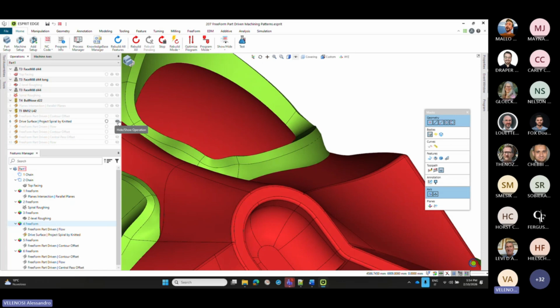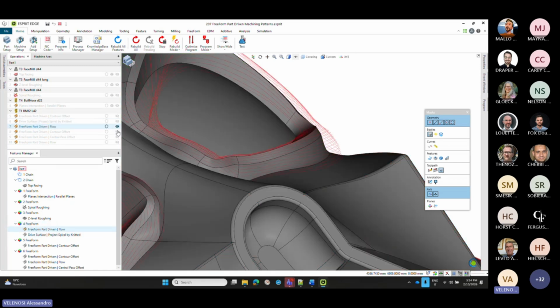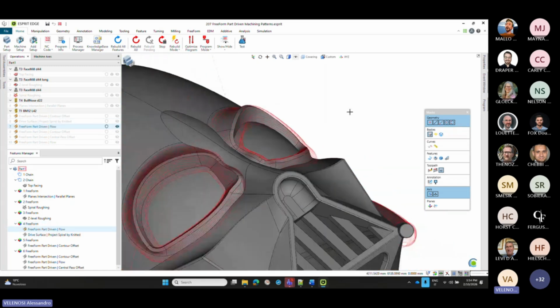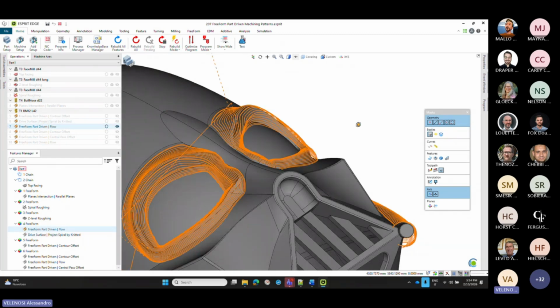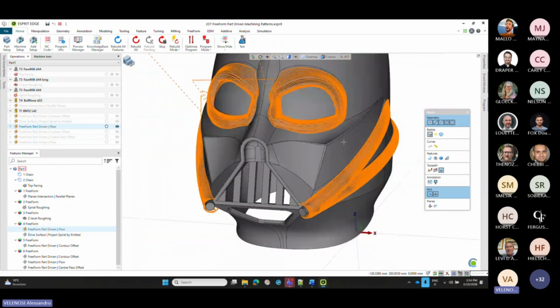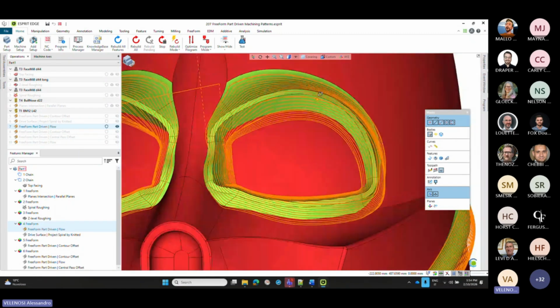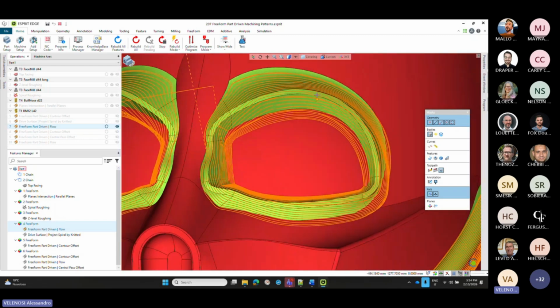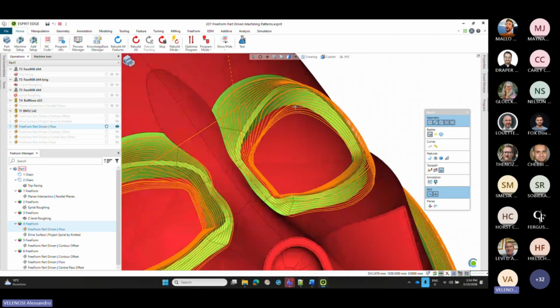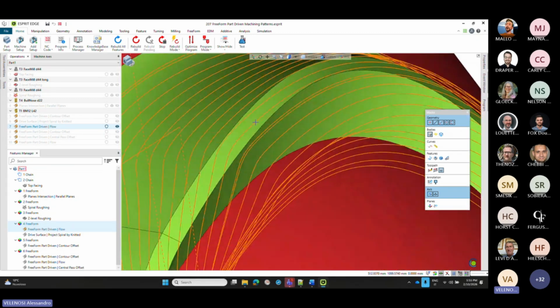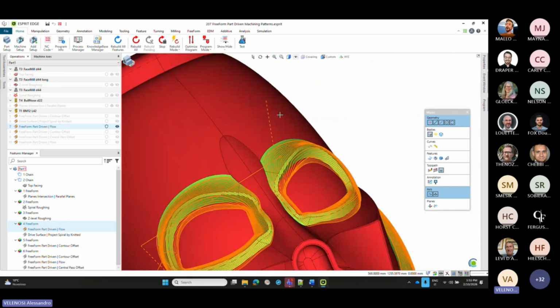So flow machining pattern is not affected by this limitation, so we can see it. And we can observe, of course, the best toolpath quality we can achieve without those interruptions in the bitangency on the outer border, but we can also observe the continuity of the passes and the regularity on the sharp edges.